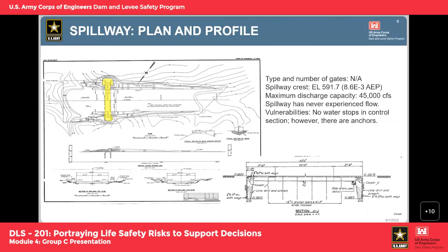Though there were no seepage problems or drainage problems encountered during construction, the design included a drainage system placed under the structure to relieve hydrostatic pressure. This drain consists of a 6-inch perforated collector pipe surrounded by gravel and discharging through weep holes near the downstream slab. Unfortunately, the system has never been video inspected, so the current condition is unknown.